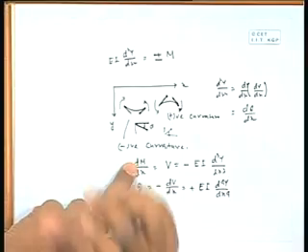From the physical look you can get the idea it will be at the center, it may be somewhere intermediate, but you have to determine what will be the maximum value and where it will be located. You can find out the value of moment, because if you substitute x equal to how much from the equation you can get it, but you require the information where will be the location, means what will be the value of x. So, in that case that will be very useful, where moment will be maximum.